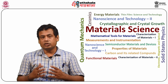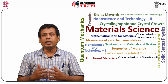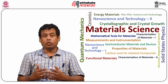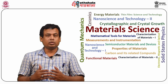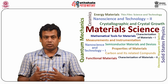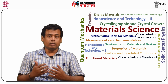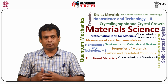These direct writing systems have the advantage of extremely high resolution and the ability to create arbitrary patterns without a mask. Their disadvantage is the long time taken to write large complex patterns. Efforts to overcome this challenge include projection electron beam lithography systems and the use of parallel beams.